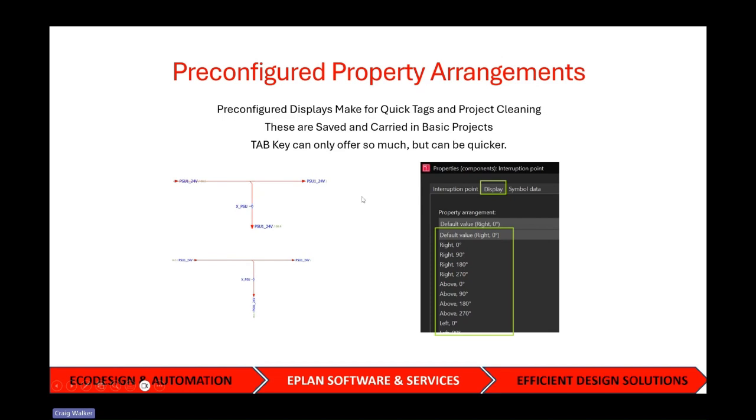So if you have a layout with a device, functional template, functional text, a technical specification, and that's nicely displayed next to your symbol with your part data, you can then save that and say, I want this to travel with my basic project, in which case everyone then knows what they're reaching for and using without having to manually configure device tags on placed parts every time, or property arrangements.